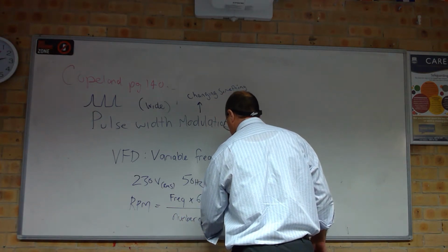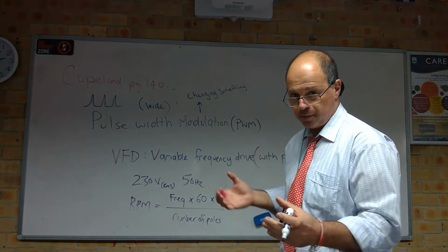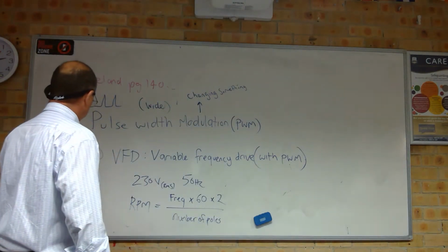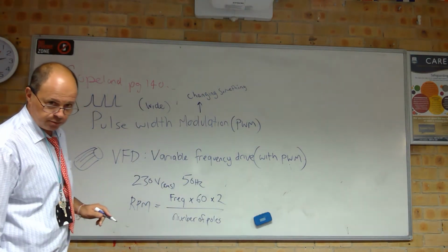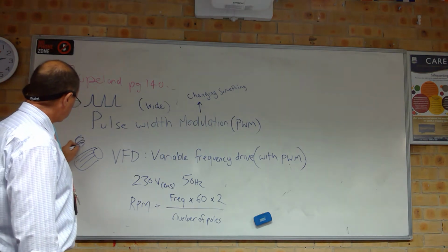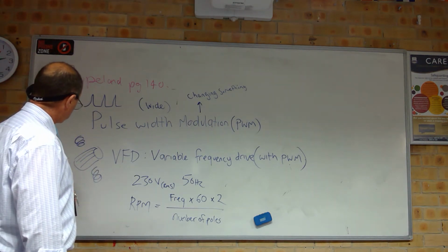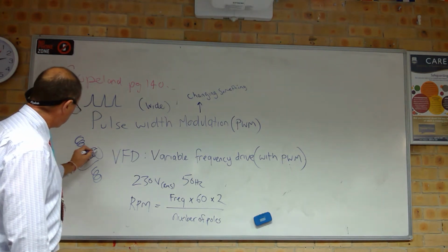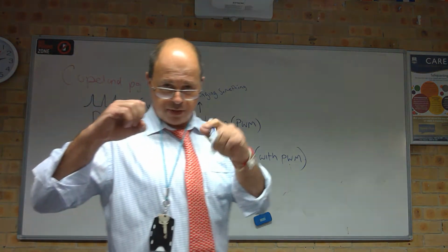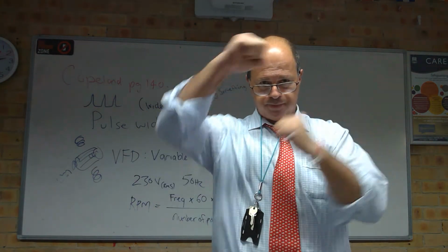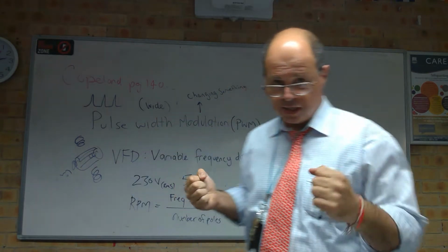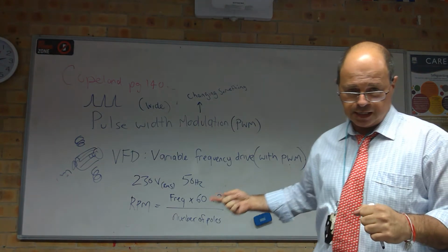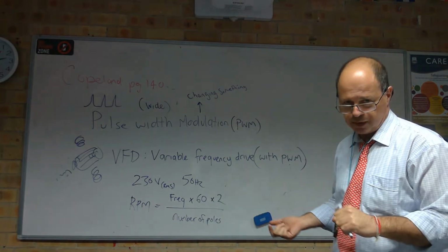of poles. On our motor we have our squirrel cage rotor in the center, and then around it we have a number of what they call wound stators, which are coils. They're not at the ends, they're around the outside of it, there might be one behind it. So they're around our rotor spinning. We have our poles. Now by dividing by the number of poles, if you divide by a larger number or a smaller number, you change your RPMs.